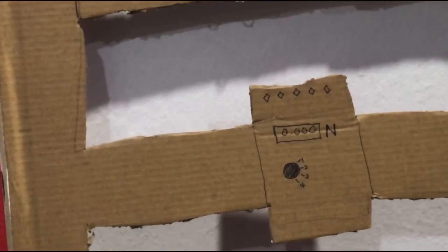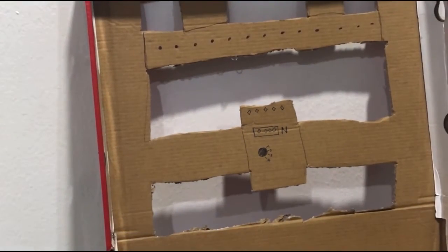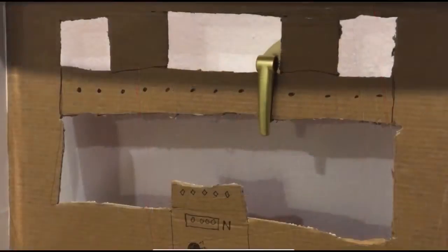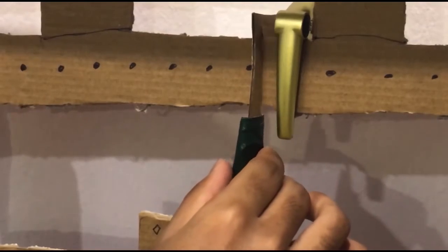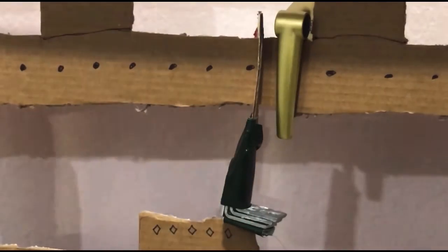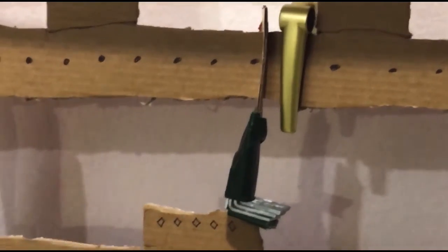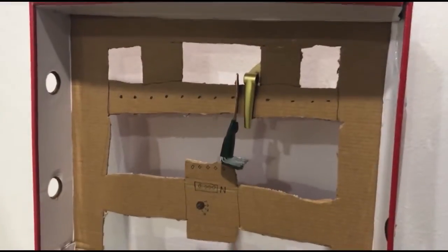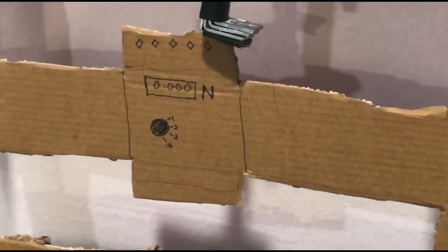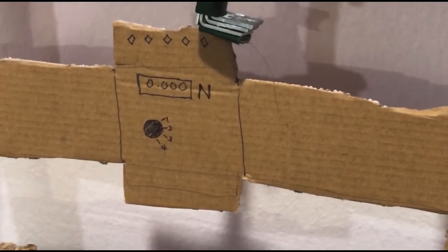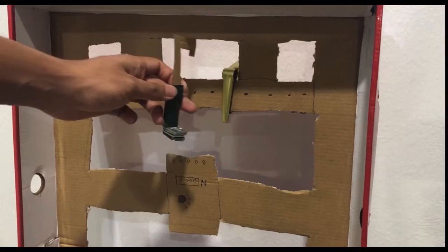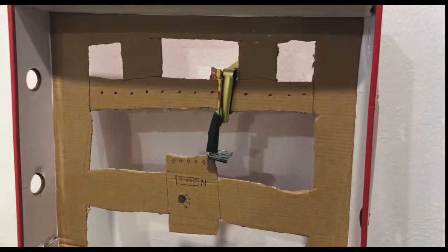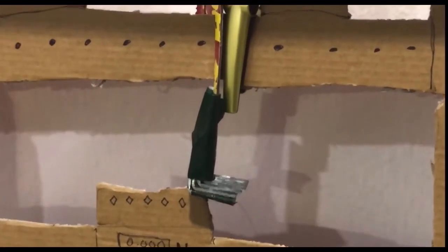First, check the digital force display meter reads 0 with no load. Next, place a hanger with a 100-gram mass to the left of the section XX. And then, record the digital force display reading in a table. This is the value of shear at the section XX. Repeat the procedure by using the masses of 200 gram, 300 gram, 400 gram, and 500 gram, and then convert the mass into load.